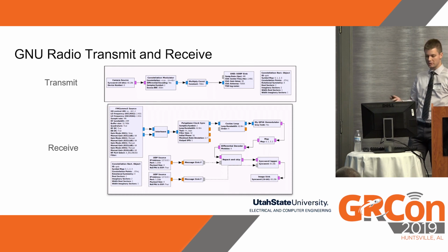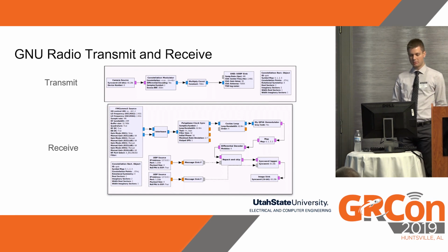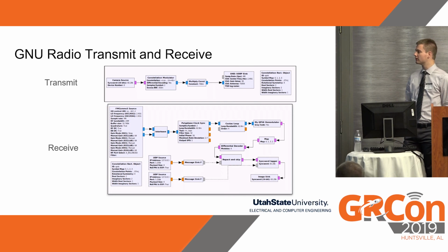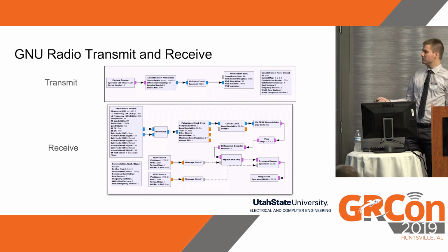This FM-Comms 5 source is provided with the reference image with the board we were using, but it's been modified here. Normally you have two different channels here, independent channels. But what this is actually sending out is interleaved samples from the coherent wideband signal that's been reconstructed in the firmware. And the reason for that is because, of course, since you have double the bandwidth, you've got double the sample rate, twice as many samples. So the way we handled that was just interleaving those samples between two of the channels.